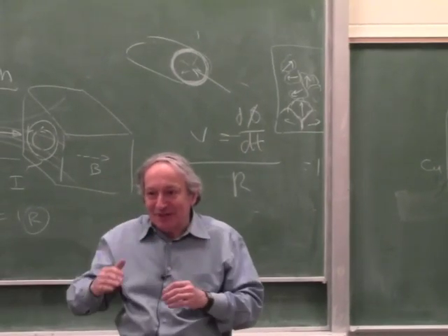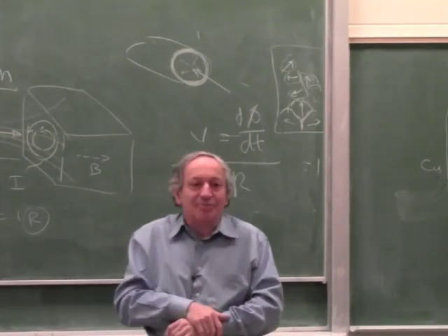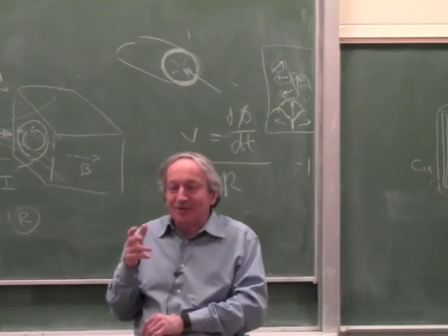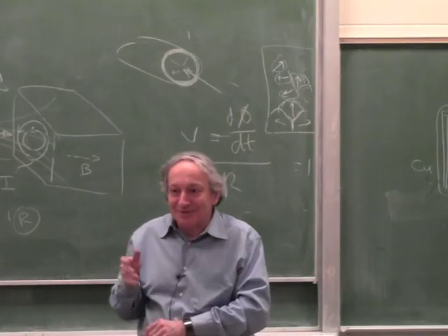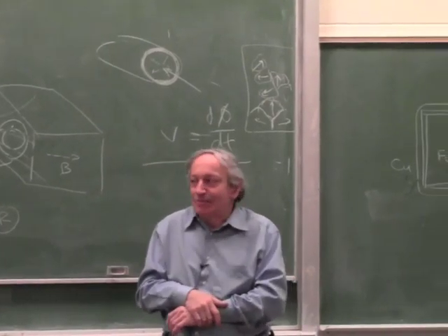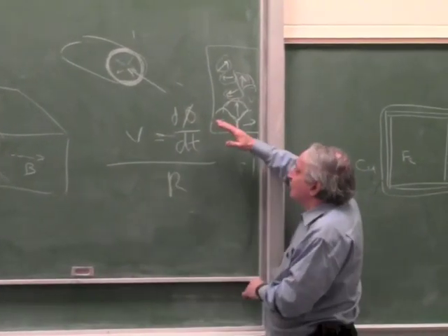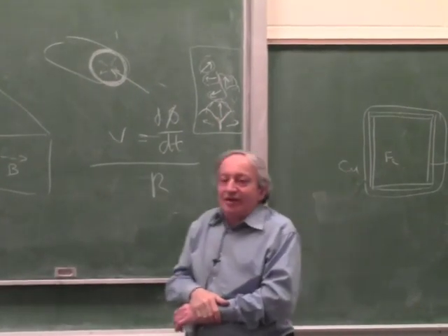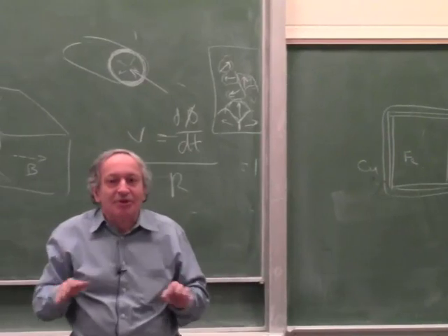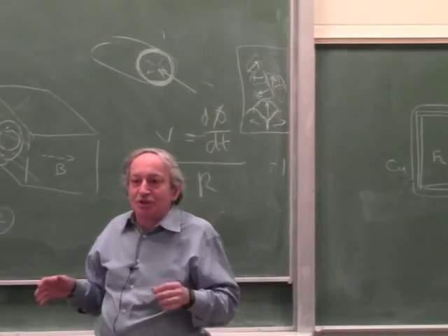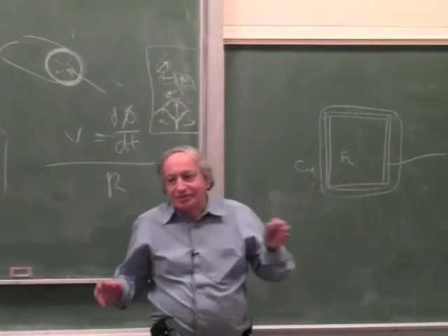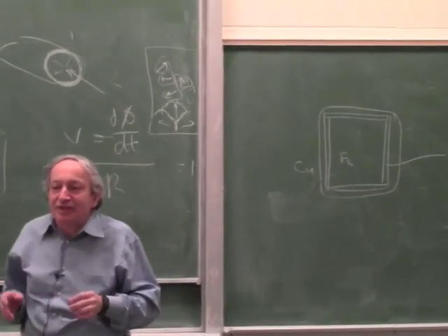There's a whole bunch of effects which take place. You can read up on it. The interesting thing is that all these effects are visible. You don't need fancy labs to see it all. So the bottom line is that shielding is not such a simple story. Sometimes you have to build a special box with two metals, the right metals, if you're dealing with very low signals.